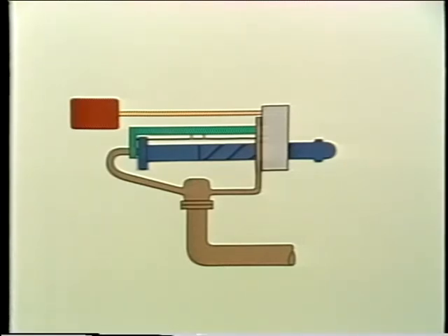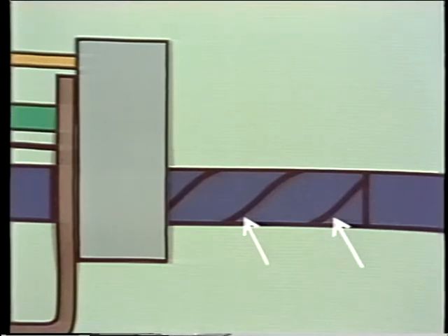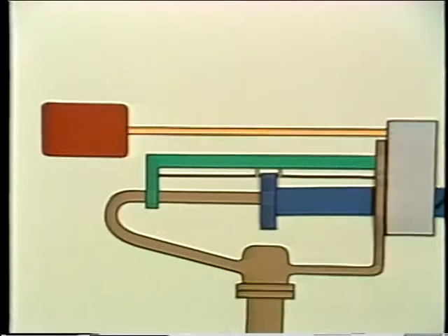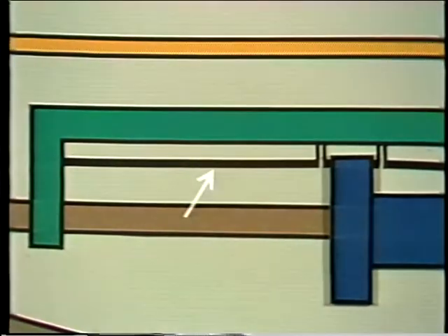On a retractable blower, however, there has to be some way to move the element in and out. One way it can be done is to cut a pair of spiral grooves into the length of the element's tube. Two pins on the inside of the gear ride in the grooves and drive the element out and back in. The element is kept from rotating during its travel out and back in by the cam guide.